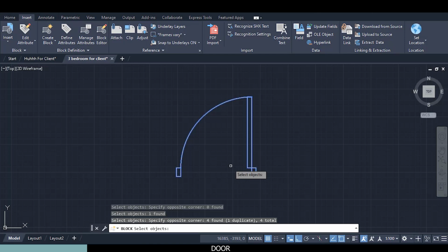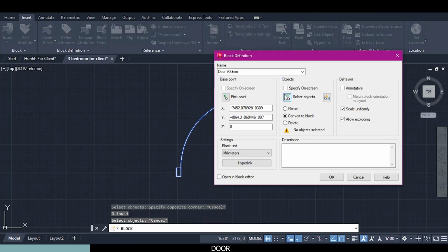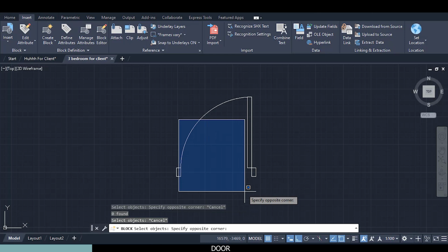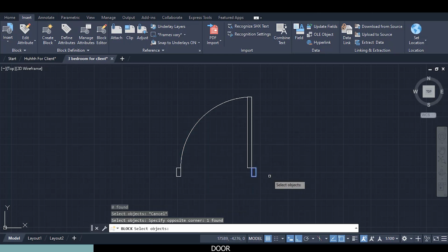And why the cross selection is the most powerful is because with the window selection, I will just press escape, press select object again, you have to select everything. Like now, only this rectangle will be selected, as you can see, because it has to be fully inside the window before it will be selected.